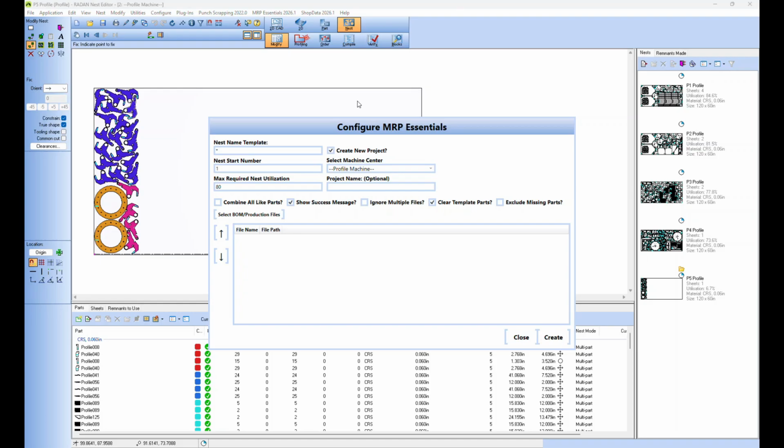And then let's say we had our one file that got converted to 6, so now we've got 6 files in this list. And if we're going by due date, perhaps, then we could arrange those due dates by the calendar day, and then we could have them processed. Exactly like what the Ultimate Nester just did, where it's only going to have access to whatever files we gave it, and it's going to nest them up. Then it's going to go to the next file, bring in extra parts, take out.